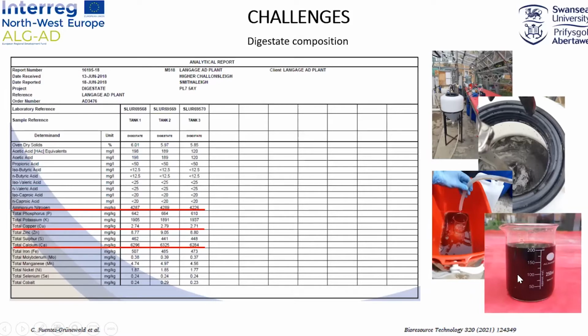That is why we thought at the beginning, when we wrote the proposal, that we were going to use around 20% of digestate. But the truth was that with 20%, the transmittance in the clean water was below 50%. So it was a really brownish water, and we weren't able to use it, because algae cannot grow in there, and also the ammonium content was really toxic for them.